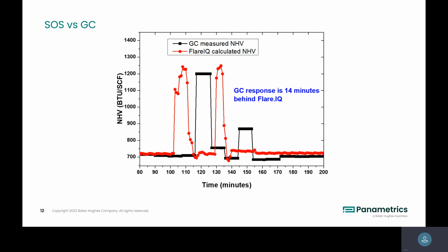So the way we come up with the density is from sound speed. You can calculate molecular weight or the density. That's the beauty of this: you don't need extra stuff. You already have it because you have an ultrasonic flow meter measuring flow. All you need is pressure and temperature.